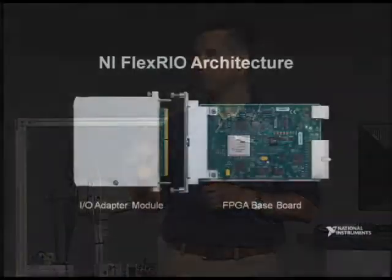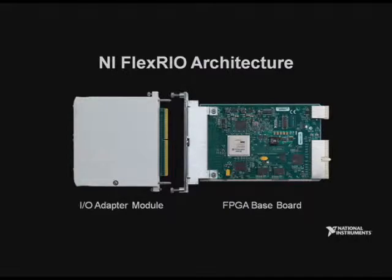Another really important part in that last demonstration is that you used our FlexRio product. This is a very important FPGA product because it's modular. It has an FPGA baseboard and then interchangeable adapter modules so that you can swap out and meet different applications with the same basic product platform. This flexibility is really important for both you and for NI, because as your application requirements change, you or NI can build new adapter modules and use FPGAs for new applications that we hadn't thought of yet when we're building a standard product.